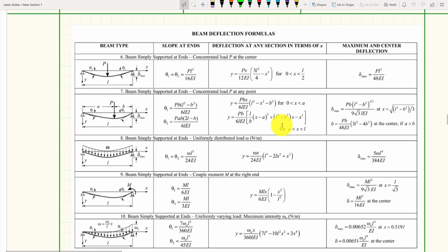Now, in your strengths books, and you'll do this in class, we talk about deflection, and you're going to be measuring deflection in this lab. We talked about in the other video how to measure that. We're going to probably have a simply supported beam here, put a load in there, and your books have equations for finding the maximum deflection. So this is deflection maximum, and we can put in our load, the length of the beam, and our values for E.